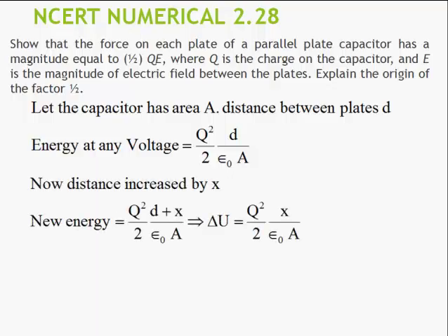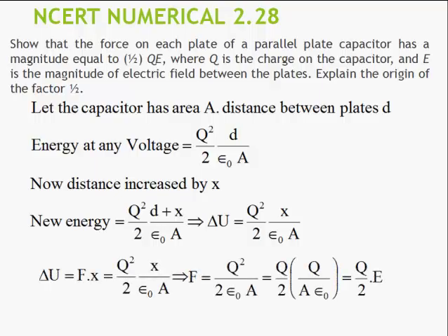So this is the new energy now. I have taken D plus X here. But when you try to find the difference, you will get this. That is the difference between the energies. Now this energy difference should be equal to work done. There lies the basic concept, F into dx. So we try to find F and we try to simplify it.